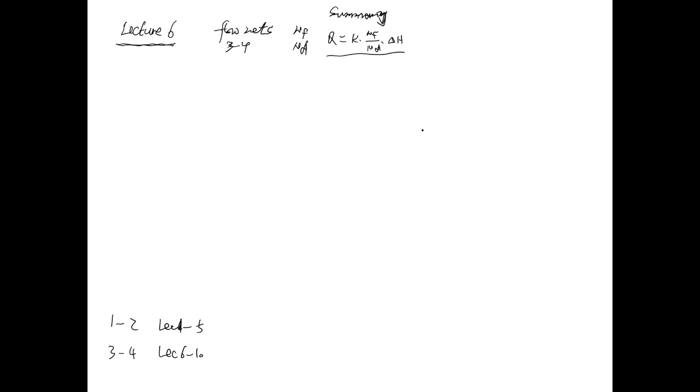What I discussed right now are the main points of each lecture. So hope you can get some hints to prepare for your final. The seepage calculation and how to count NF and ND are all very important. And next, once you get the flow lines, you have to know how to work out the water height, the H of each equipotential line.